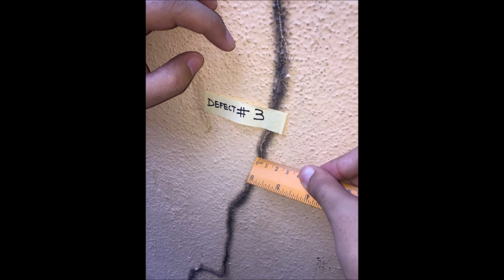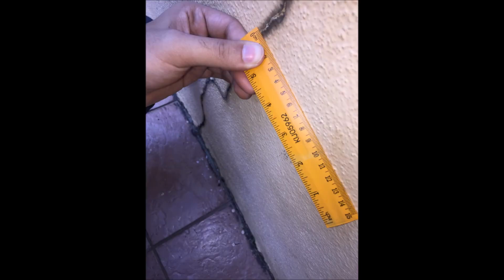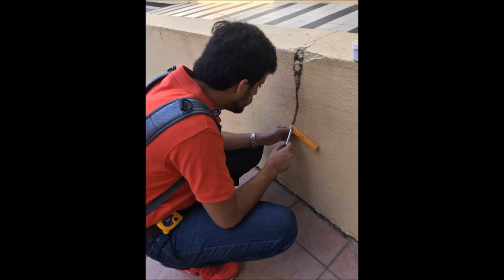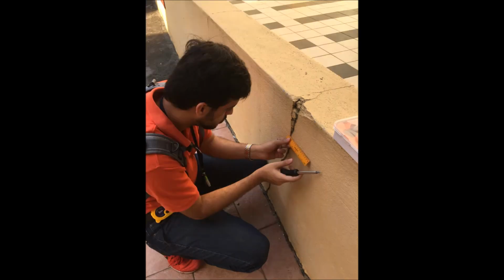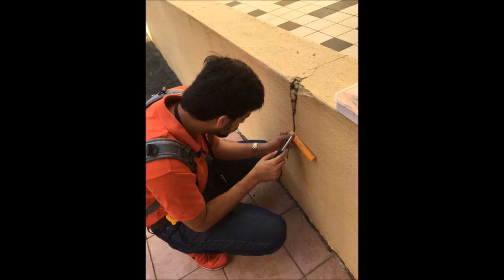The coefficient of thermal expansion of brickwork in the vertical direction is 50% greater than in the horizontal direction, because there is no restraint to movement in the vertical direction. Thermal variation is mainly in the external walls, especially walls exposed to direct solar radiation, and the roof. A second diagnosis could be improper selection of the material or selection of poor quality cheap materials.